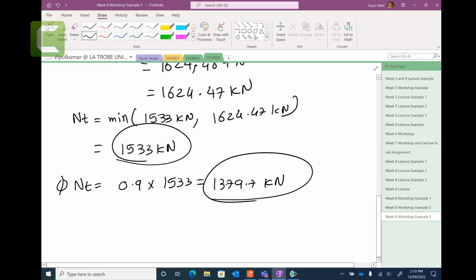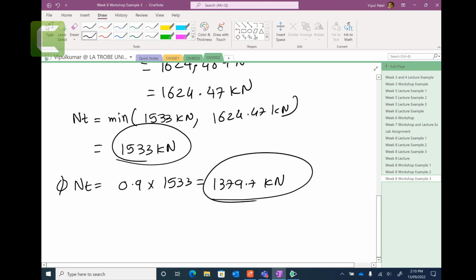They heat up the materials, and as you know, when you heat up the materials, they reduce their yield strength. We don't consider this in our subject, but when you heat up the material and you see it red, it becomes brittle. When it's cooled down, it becomes brittle. If you are considering 300 megapascals, you are not going to get 300 megapascals. It might reduce to 200 megapascals. It's not part of this subject, but sometimes you need to take that into account. Any questions or any